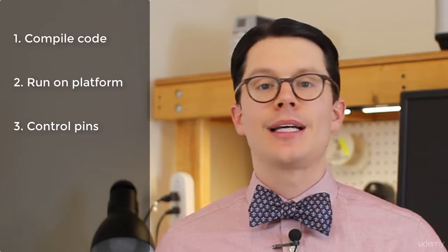When it comes to programming microcontrollers, there is a first program we can write that is quite simple and it tests functionality. All we have to do is blink an LED. This program, lovingly known as Blink or Blinky by embedded engineers, tests the basic functionality and is the microcontroller equivalent of Hello World. By doing this, we prove that we can compile code with correct syntax, run it on the microcontroller without any hiccups, as well as toggle voltage levels on pins.